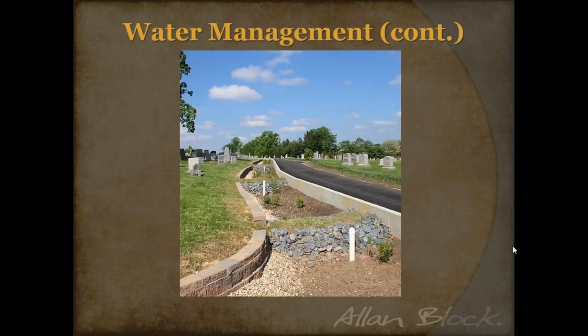If you noticed in that one detail or one picture, maybe some of you noticed that they did bring in some select structural backfill here, probably a little bit for erosion protection. So if the water comes in, it's not going to undermine that wall. So it's a very simple way to bring in some of that crushed rock as we go through.